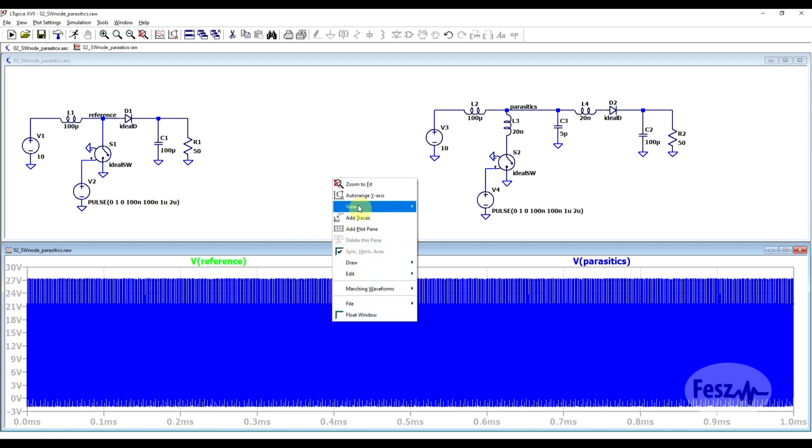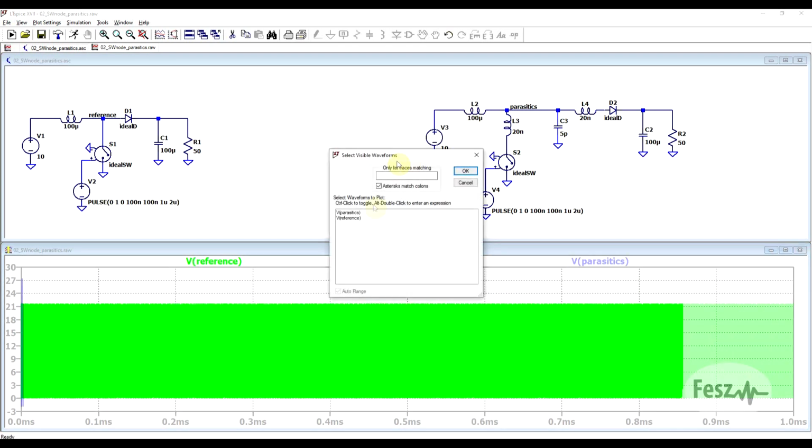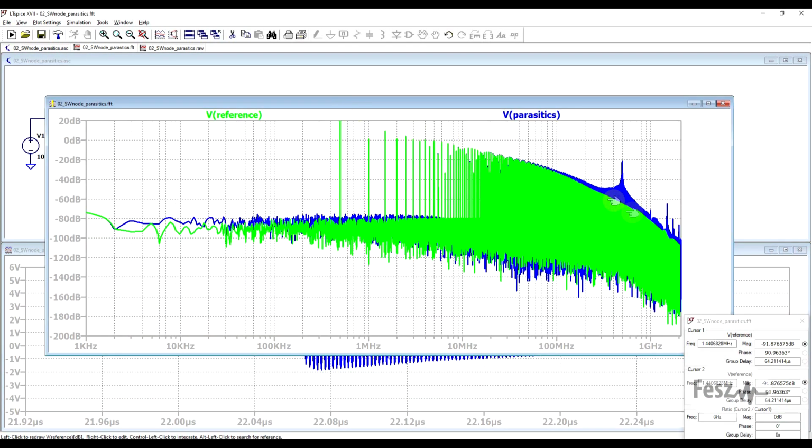And if we want to analyze the spectrum of this, again using the FFT analysis, on top of the noise spectrum of the signal that we previously had, the one in green, by adding the extra parasitics and thus the ringing, in the spectrum we are seeing some noise peaks appearing, which are not really derived from the switching frequency. But these will be larger the more high frequency energy there is. So these could be reduced if you increase the transition times, although some better methods do exist.